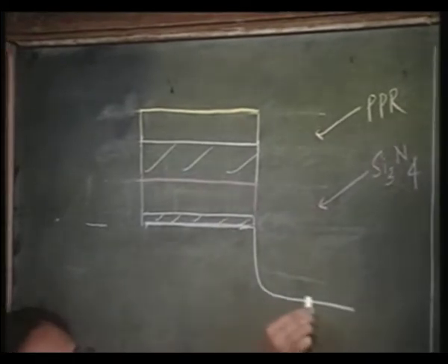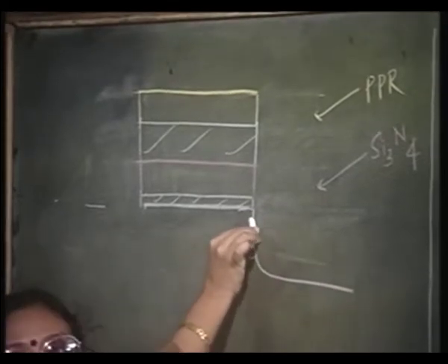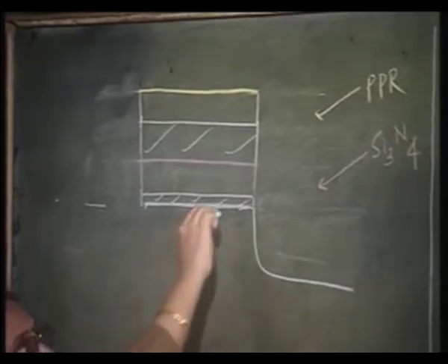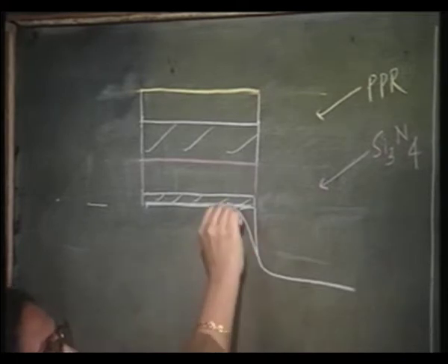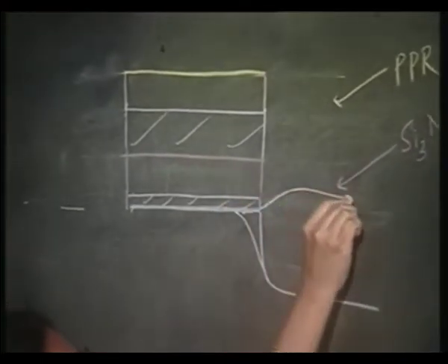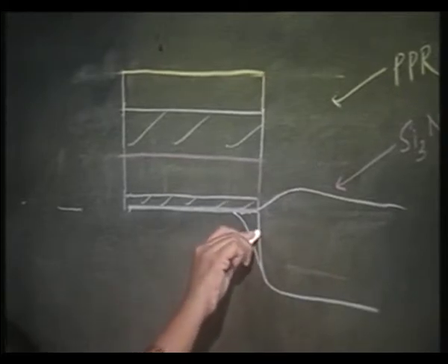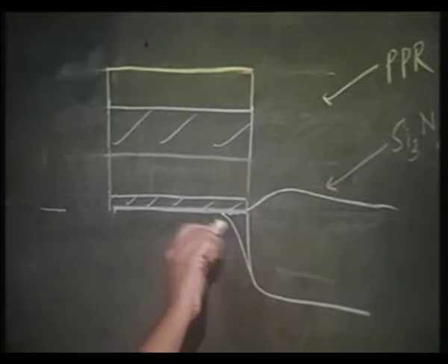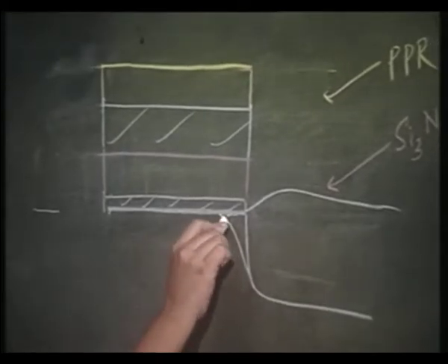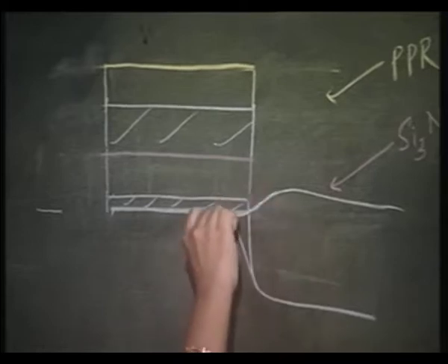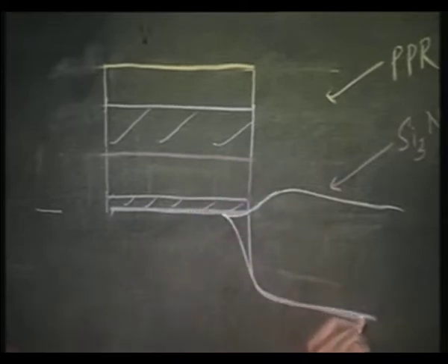So, not only this surface of silicon, but this surface of silicon is also available for oxidation, right. So, obviously now it is going to project more and actually you are going to have something like this, because oxidation is also taking place on the side wall. So, there also it is going to have some oxide underneath that surface and some oxide above that surface. So, what you are going to have is a shape like this.